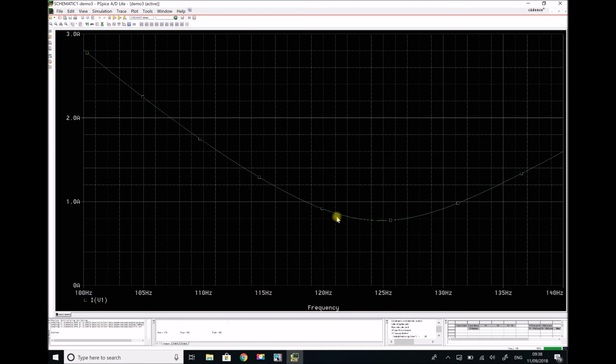So what we can see here is we have a frequency of 120 Hz up to a frequency of 125 Hz, and the lowest point there is just below 125 Hz. So around 124.5 Hz. Now I actually ran these calculations manually and I found that the resonant frequency was 124 Hz to the nearest whole number. So we know that we've been able to replicate those results.